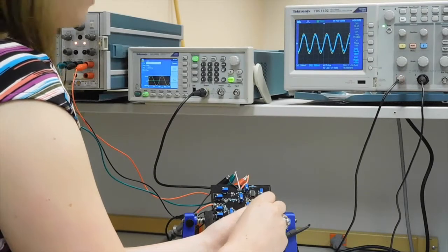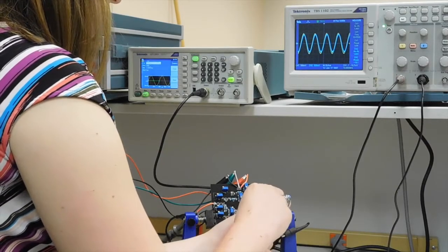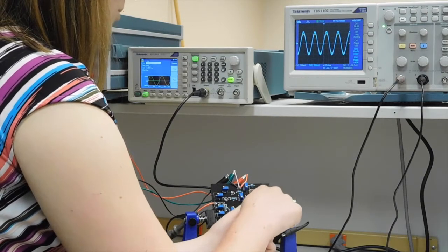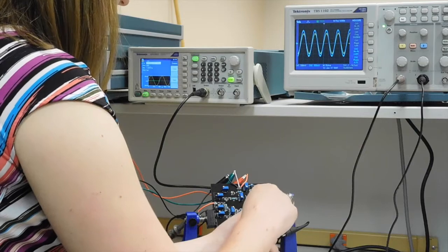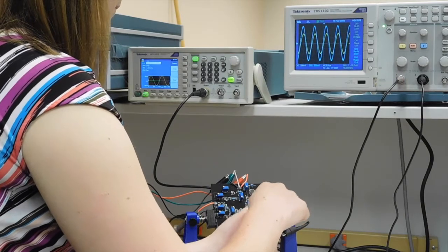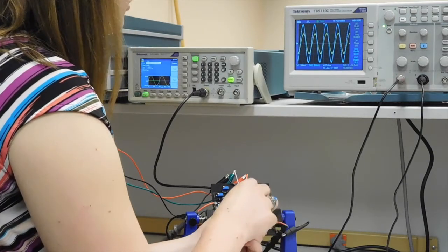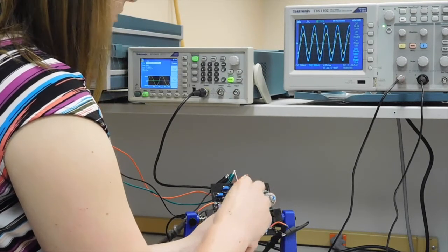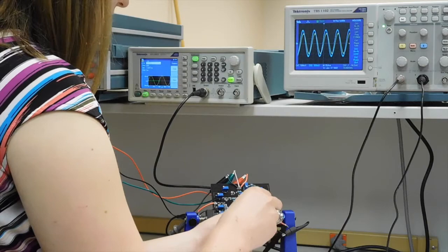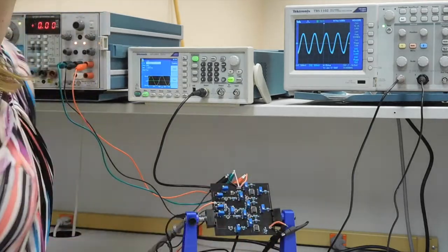I'm now going to demonstrate our fifth and final band, our high-pass filter, operating at 18 kilohertz. As with the other bands, I'm increasing the feedback resistor, and you can see how our output signal is increasing substantially as our feedback resistor is increased. Our cutoff doesn't happen quite as quickly as our low-pass band, but you can also see when we start to put it into cutoff, our waveform does decrease in amplitude, until it is completely in cutoff.